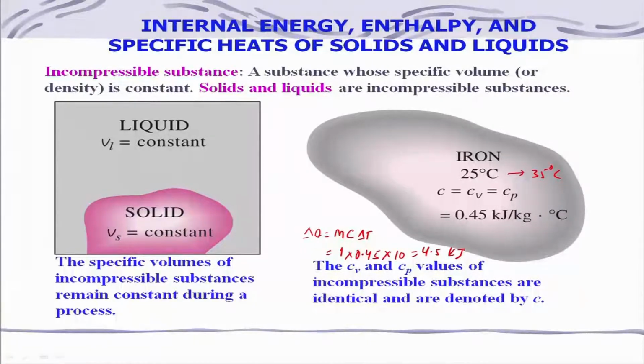But if I do this for water, 1 kg of water, and I am changing the temperature of 1 kg of water from 25 to 35 degrees Celsius, it will be around 41.8 kilojoule, isn't it, because your Cp value is 4.18, right. So, it is something 9 times that of the iron. That means the heat capacity of the water is higher than the iron.